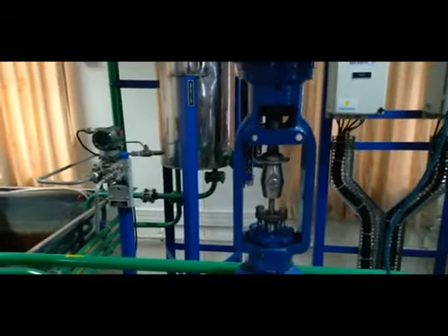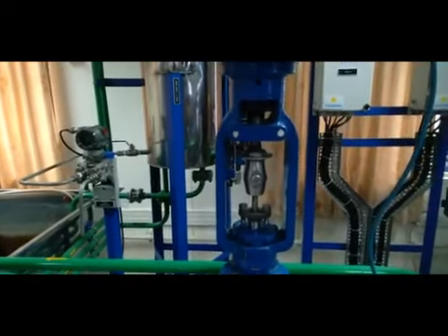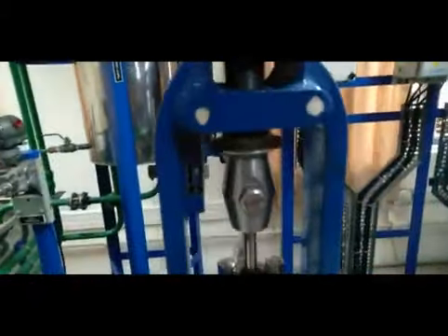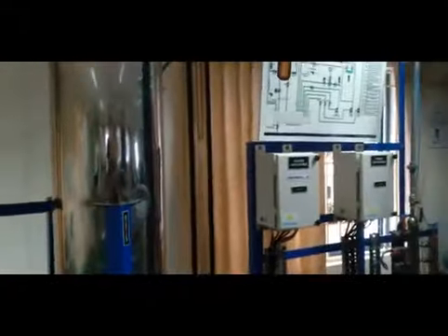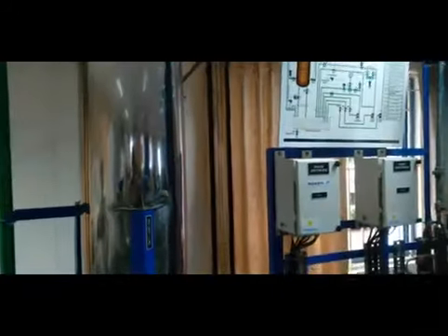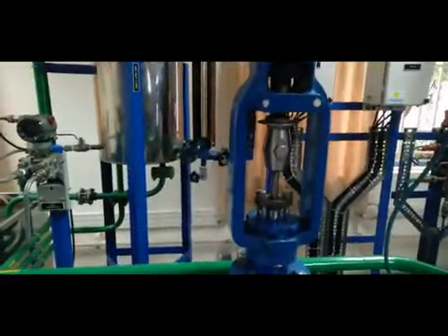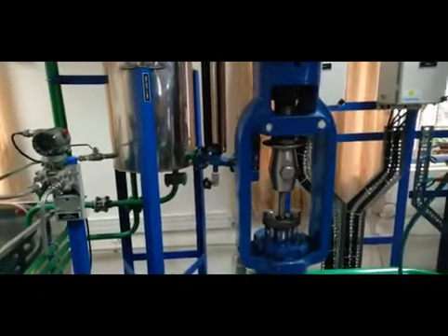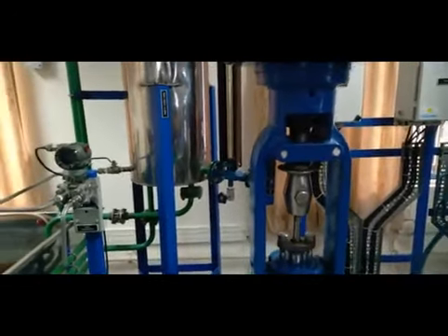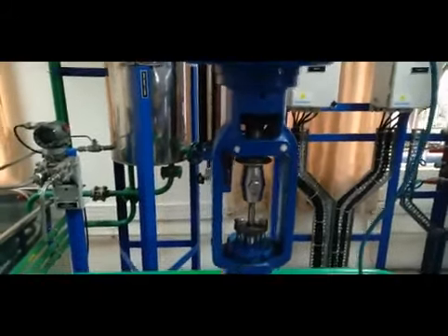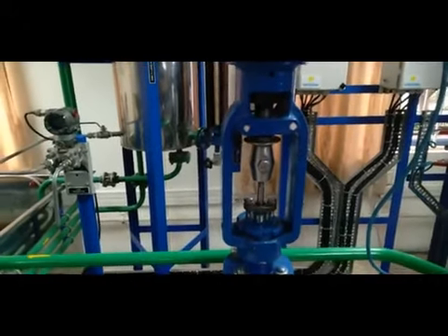Since we have implemented a PID controller in this, you can see this control valve closing, and now it is open, so that the water level goes above. You can see that the water level goes above our set point. We are already aware that whenever you use a PID controller, there will be a change in height. It will come, then it will take action, so now the water above that level will be dispensed, and we will be seeing how the trends are coming from the computer window.